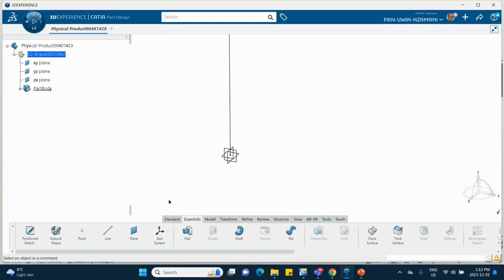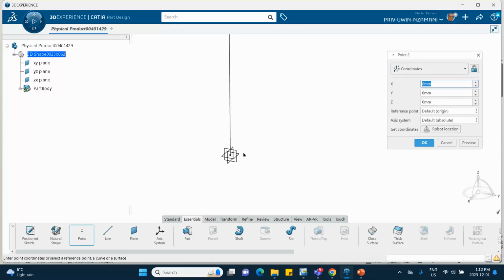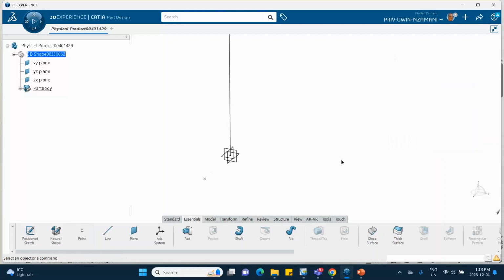That being the case, it doesn't matter where I create the point, but I will create it with, let's say, maybe 200 millimeters on the x-axis. If it's too short, we can change that. Preview. No, maybe 1000. Preview. Over here. Okay, actually, let me make it a little bit longer. Maybe 2000, so that I can see it better there. So we have this point here, which is going to be used as the orientation point for the beam.